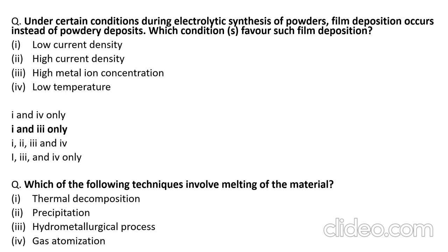So it is gas atomization, in which the molten material is poured through a nozzle, because of the melting of the material. So in gas atomization, the material is melted first, and then it is atomized in the form of spherical balls in a gas atomization chamber.